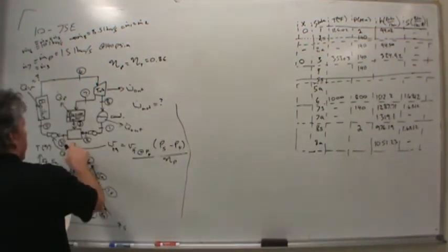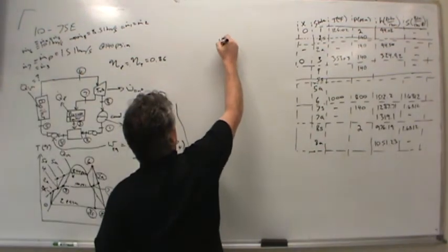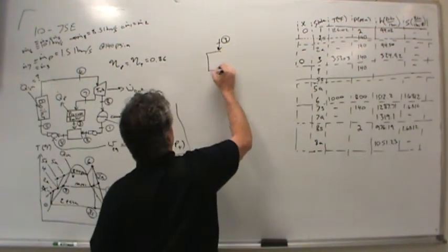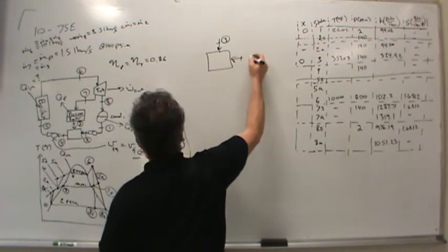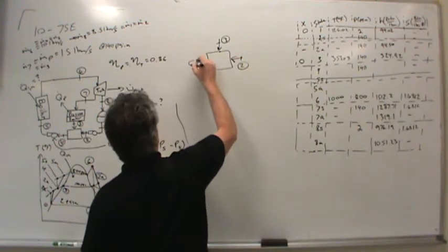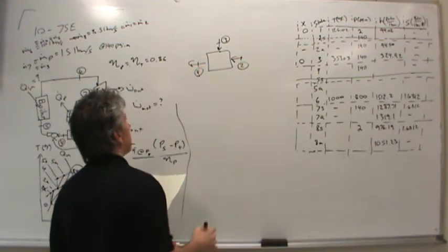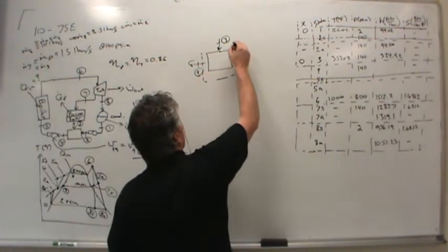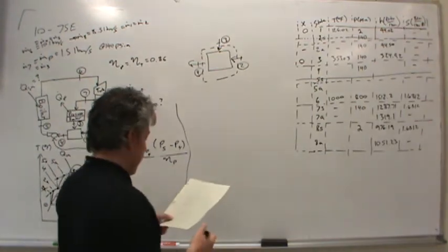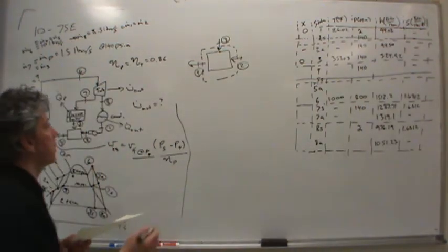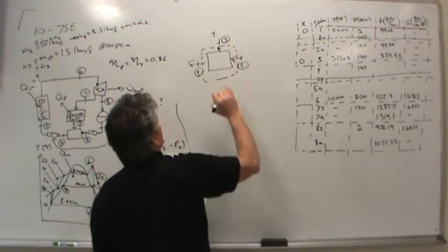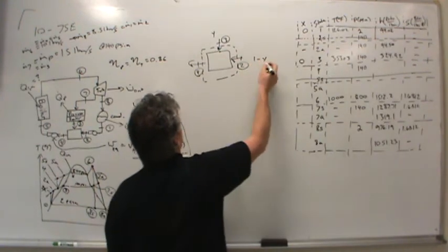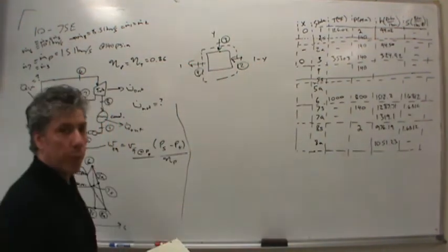So this mixing chamber right here, you copy it. State 3 comes in, state 2 comes in, and state 4 leaves. Now, if I were to write an energy balance around this, I would like to write it in terms of mass fractions, because y percent goes this way and 1 minus y percent comes in this way for 100% output.